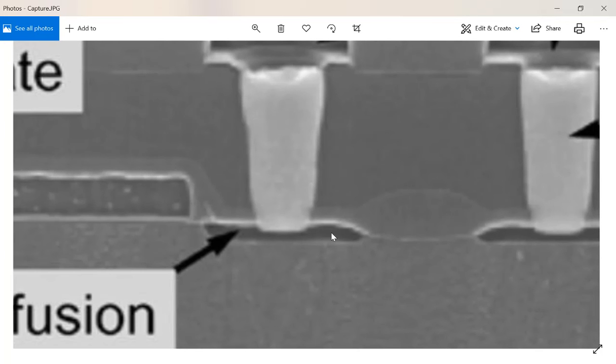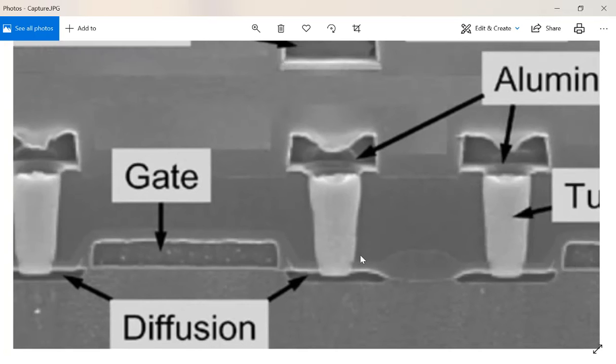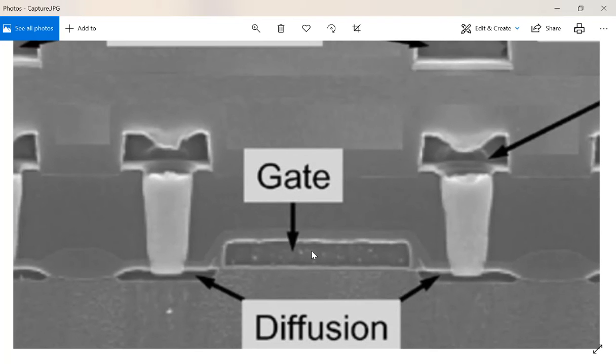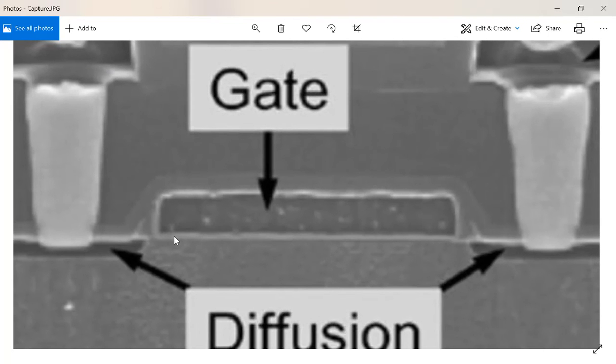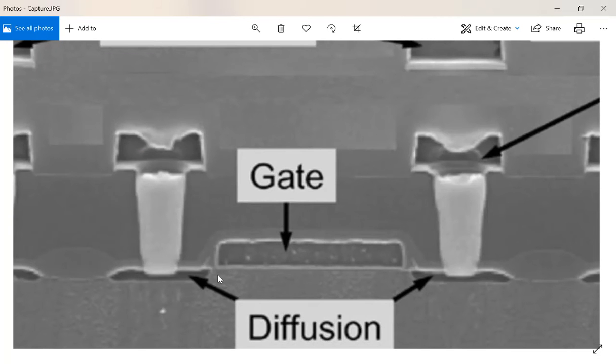So the Fox can first protect all these layers from getting shorted, and also reduce the crosstalk between these signal lines. So signals are not easily getting through, or the high frequency AC signals are not just shorting this terminal, since they are super close, like in nanometer level. And here's a gate. You can see Fox is also on the top of the gate as well. And there's a really thin oxide layer underneath the gate as well. It's called gate oxide. You couldn't see here, but it's super thin, right? So the gate is not shorted to the channel. So here's the channel, right?